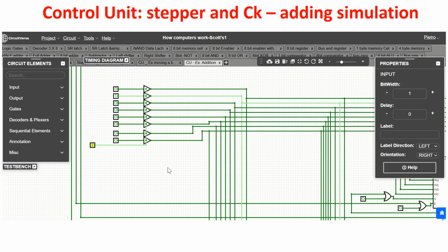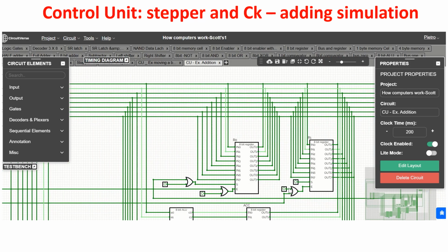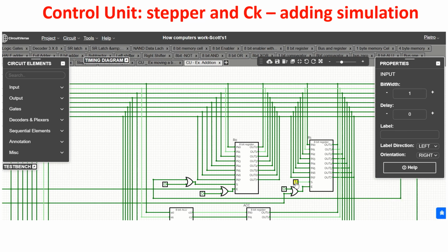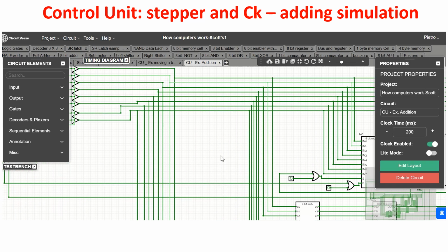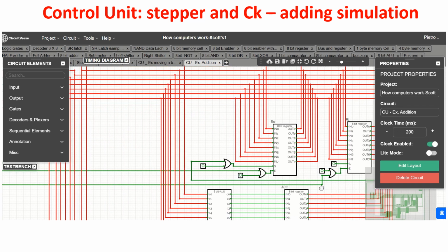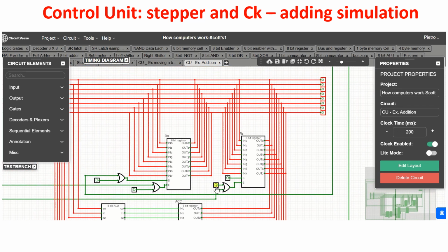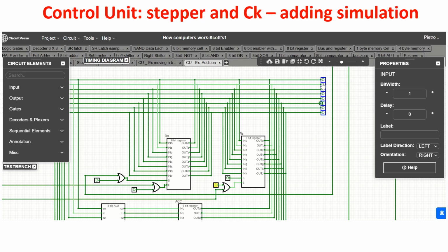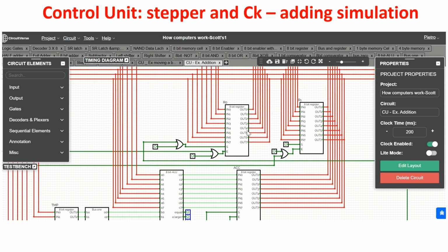So we put the number 2 on the bus and we give a set pulse to R1. So we free the bus. Let's check what there is inside R1, giving an enable pulse, and we read the bus, there is the number 2. So we free the bus. So now there is the number 3 inside R0 and the number 2 inside R1. So we expect to find the number 5 inside R0 at the end of our simulation.